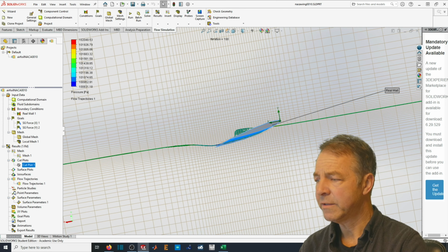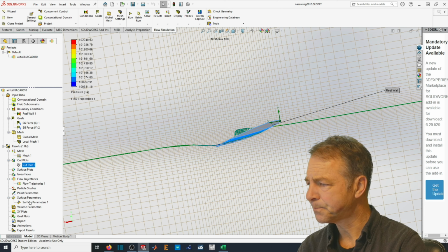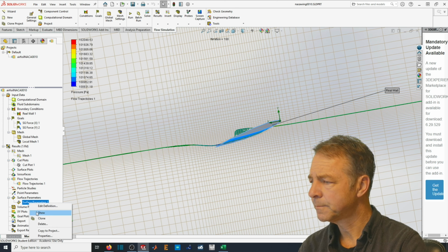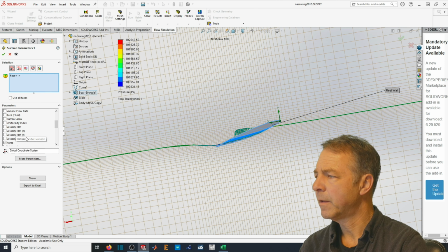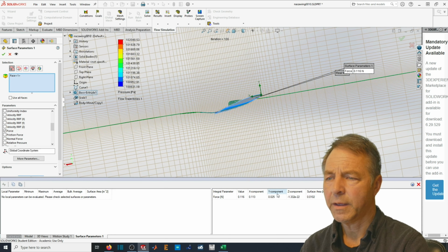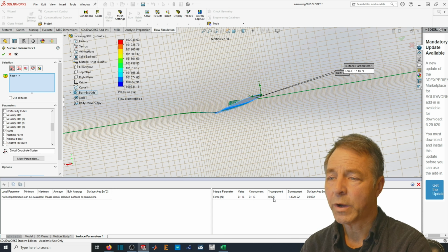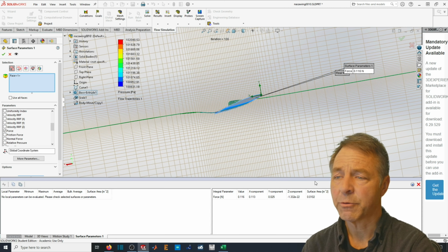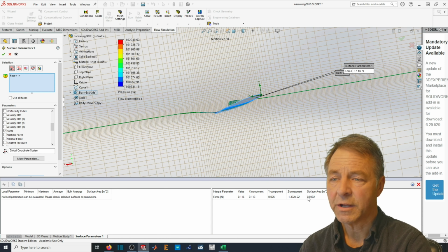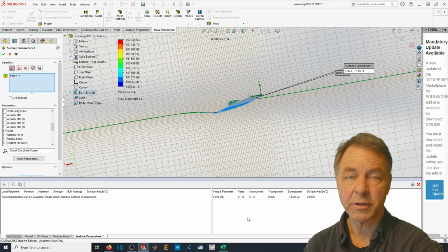But again, we can take the results of the forces, and we had an x component of 0.13 and a y component of 0.025. So here with this simulation, as I've changed it, we now have more drag as compared to the lift. And the numbers are irrelevant. They just are different because the two-dimensional model made a smaller surface area.